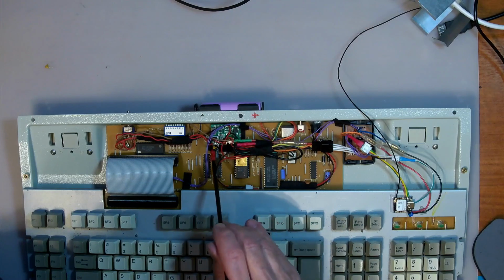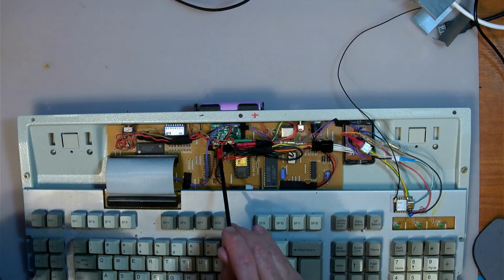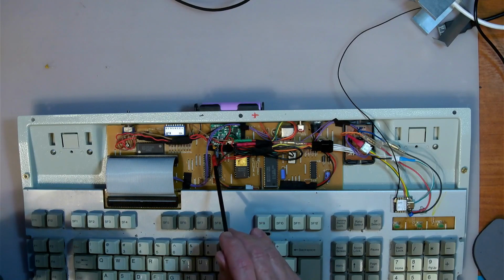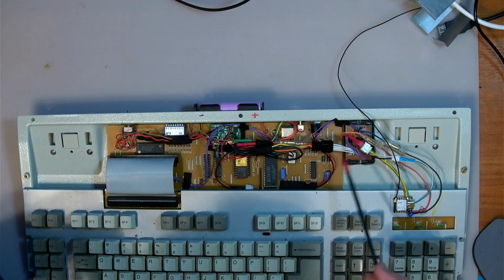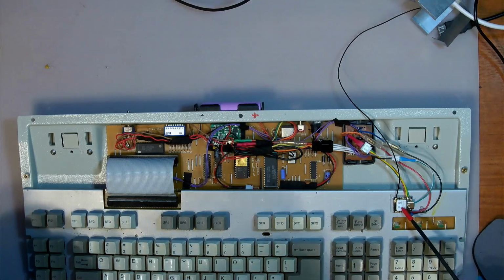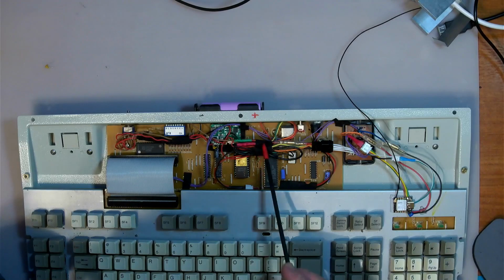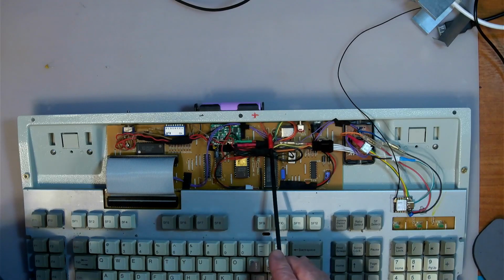These little boards here, they're not bad, but I just like to quieten down the noise. So I put a 100 nanofarad and a 220 microfarad capacitor there. I put another little 100 nanofarad capacitor on here for the microcontroller to keep things nice and smooth. And so I got that connected.